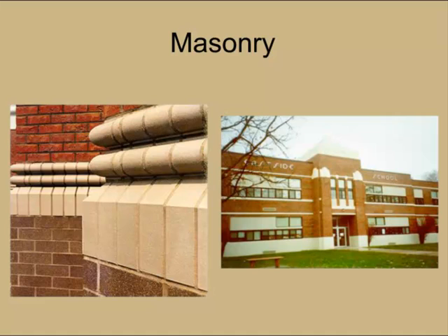Two things on this slide that we want to focus on. We'll start on the left, and this is dealing with the mortar joint profiles. If we're issuing a test, this would be a test question, but looking at the different joint profiles, extruded would be the least effective and they would gradually improve as you go up.